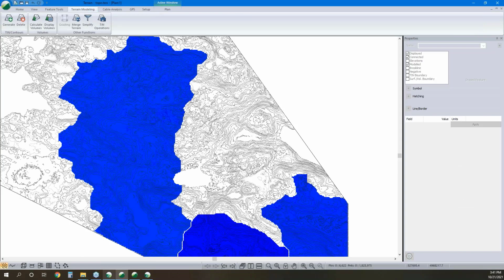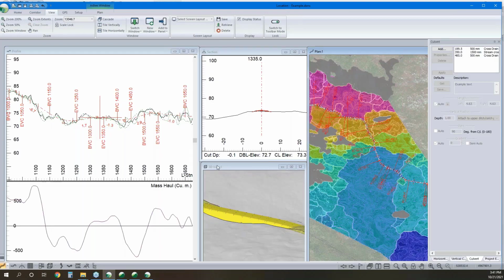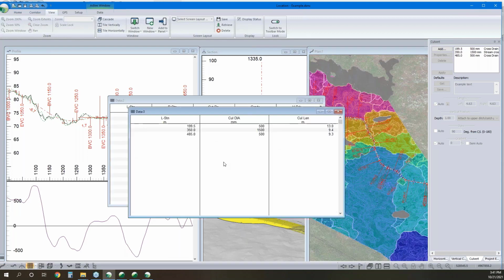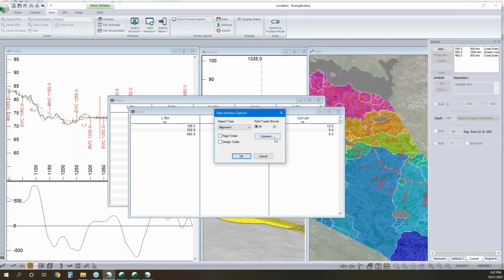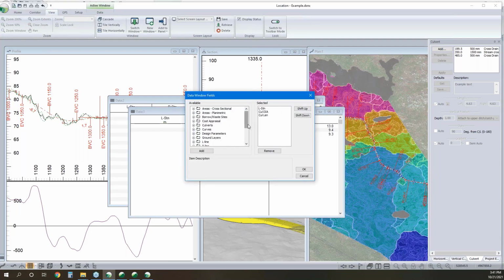Yeah, so where are we at here? We could do it in the major culvert as well, but this one has more pipes going on and I've already set up a data table. So I've added in my culverts. Now, if I want information, say for staking, in my culverts breakdown here, we can add in our inlet elevation, which would be our Z. But if you're construction staking with it and you wanted the actual points, we can add those in here as well. We could do the same for the outlet, and you could go and stake what you're working with.